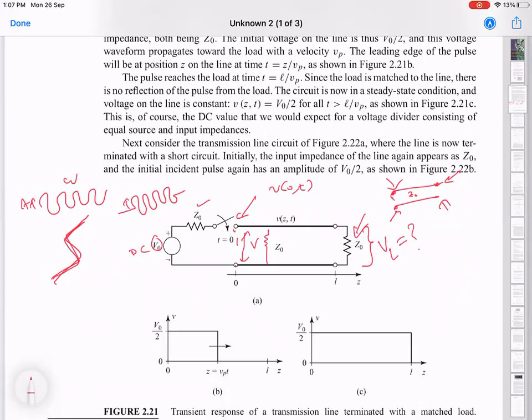So you only have to worry about the boundaries, right? Because once the wave is launched, which means you have defined E plus at that particular location, then the transmission line's job is just to propagate that along it. So the thing to think about is what happens at this particular point. If this transmission line had a different characteristic impedance than Z0, then it will be the corresponding ratio.